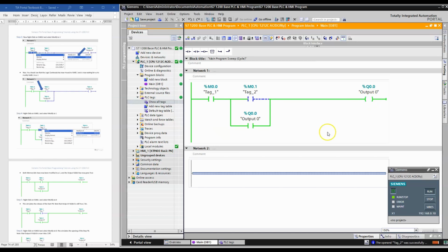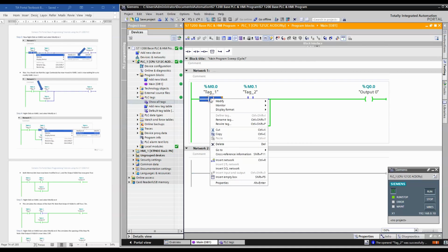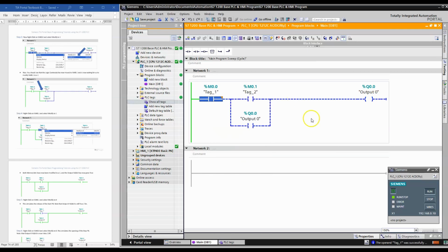Excellent. Okay, at this point, we would want to stop the 3-wire from working. So we would come over here and we'd actually physically press the stop push button. And in doing so, we would be modifying that in the memory from a 1 back to a 0. So once we modify it to a 0, you'll see that the output turns off instantly. Sweet. Excellent.